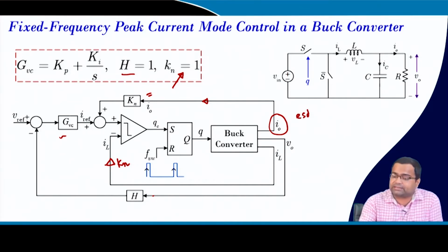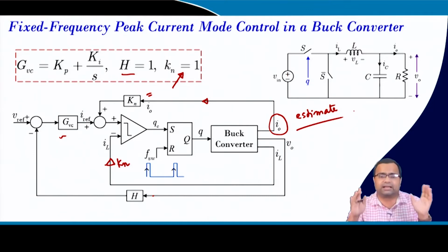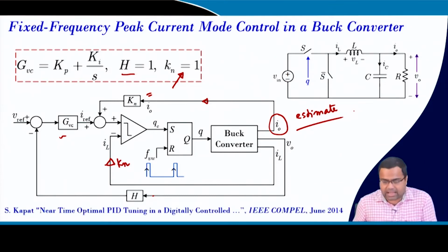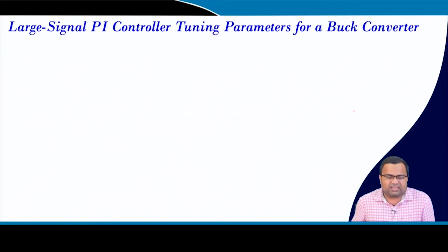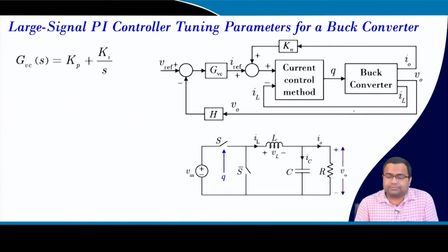So, you can estimate this load current, and we have already shown that you can even apply this tuning to voltage mode, where you do not need to sense inductor current or load current. So, that is also possible, and this is already reported. Then you can apply this technique for current mode control, which we have just now applied.